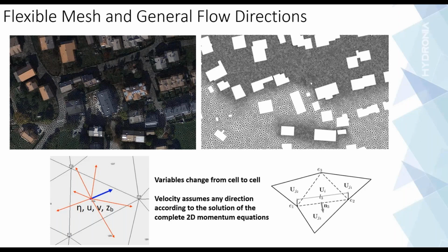The other advantage is that if you have structures like levees or even dams that do not have a rectilinear alignment, you can create and adapt those alignments in the best way to represent the real situation, and generate your mesh so that it will capture the geometry that you have in the most realistic way. That is the main advantage of the flexible mesh with respect to other models that use square cells, which are not able to adapt to a real geometry as you would have in an urban area or in a natural environment.